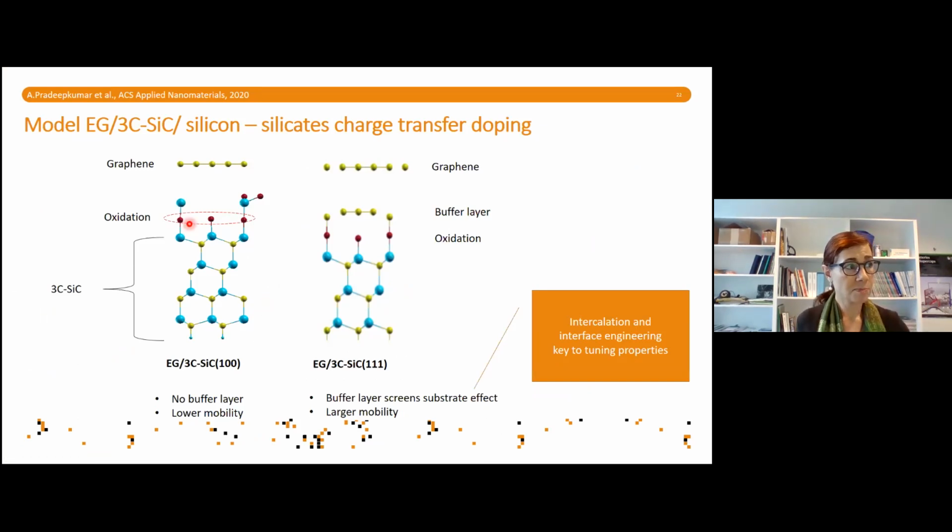Basically, as I was explaining, intrinsically when we use this approach to graphitize silicon carbide, I didn't explain the very details, but because we have oxygen in the system, and we start basically releasing the carbon from the silicon carbide, the dangling bonds combine with an oxygen.